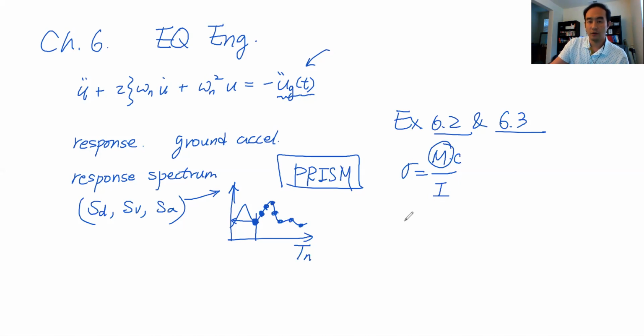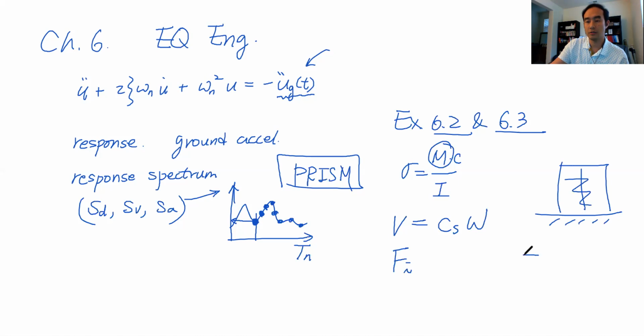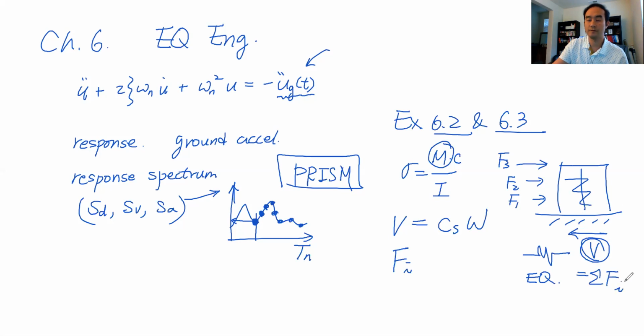And then we also talked about seismic design procedures. So base shear calculation and this F. Base shear is, let's say here we have a building structure against a certain ground motion earthquake. The base shear is going to be the entire lateral force. So when we think about the lateral forces for each floor level, let's say this is F1, F2, F3, then this V is going to be the sum of all these Fs, okay? So how can we get these numbers?